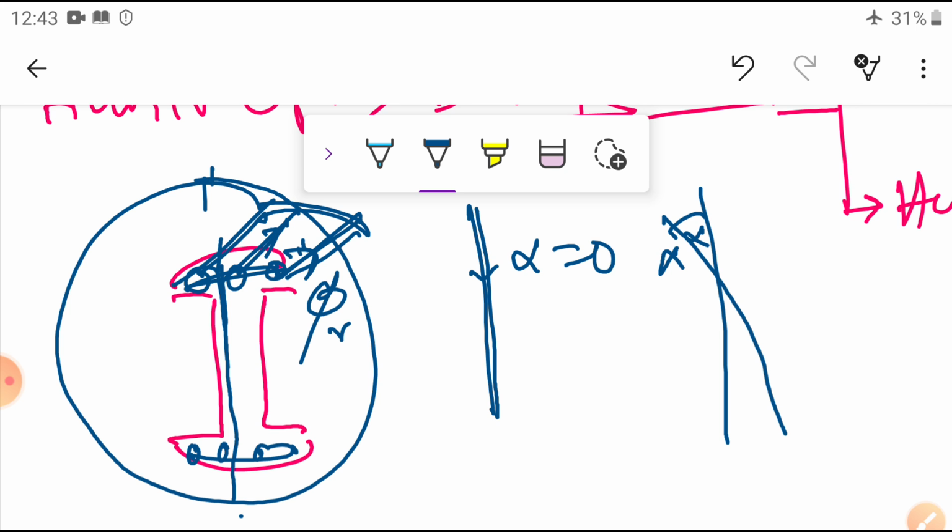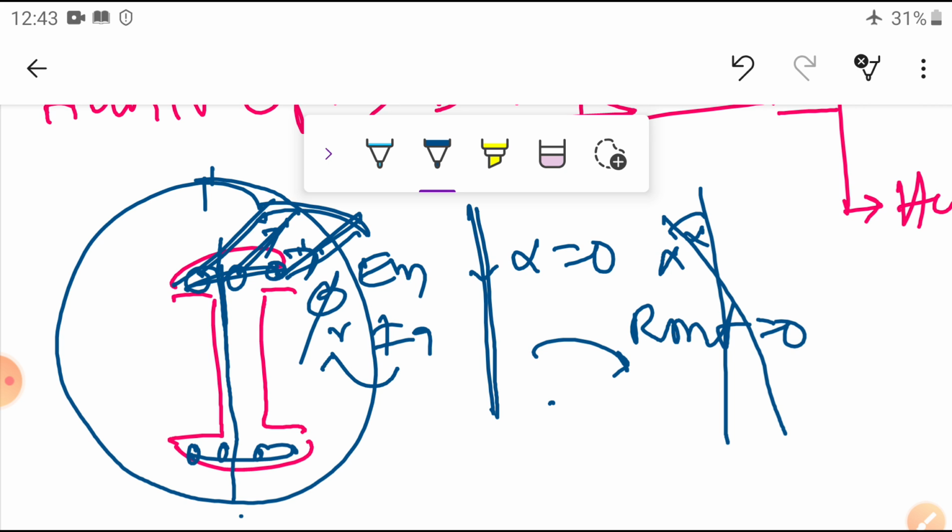The oscillation only. Under normal condition, the relative motion between the rotor damper windings and the rotating magnetic field is 0. Due to the sudden load change, relative motion takes place between the rotor conductors and the rotating magnetic field. That is why it induces its own EMF, and eddy current flows. Due to this current, the flux produced in the damper windings is always opposite to the cause of its production. What is the cause? The vibrations. The vibration will be nullified as per Lenz's law.